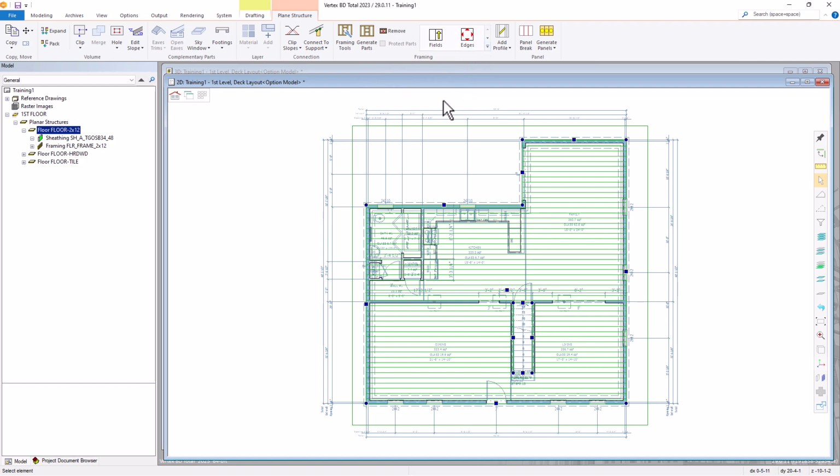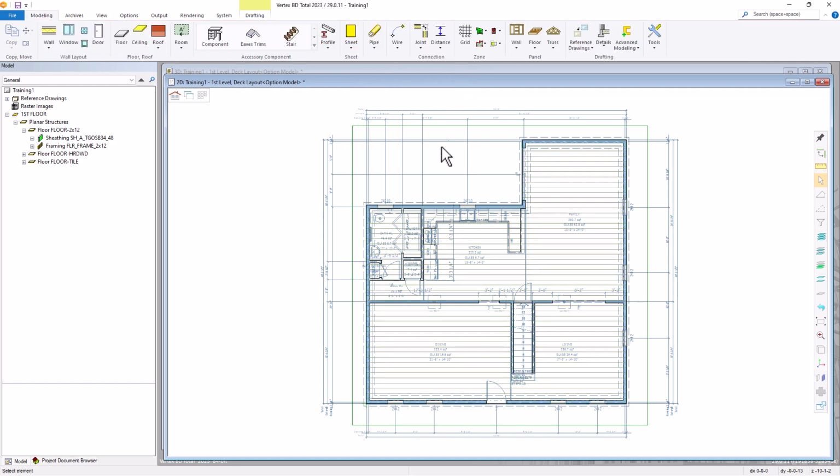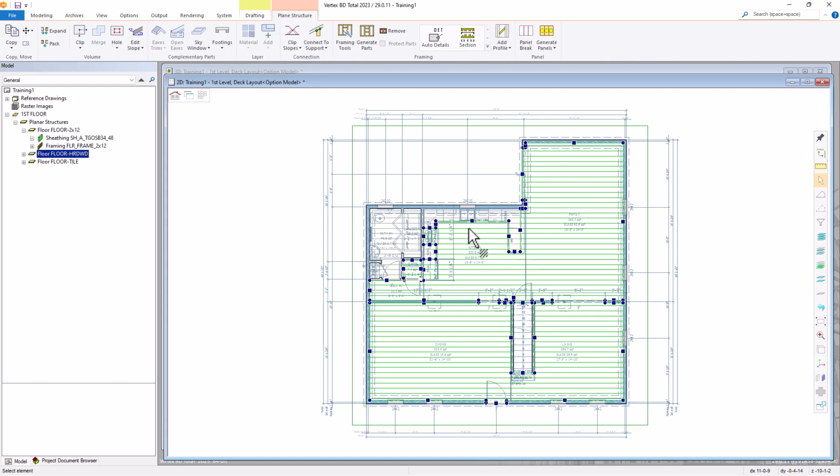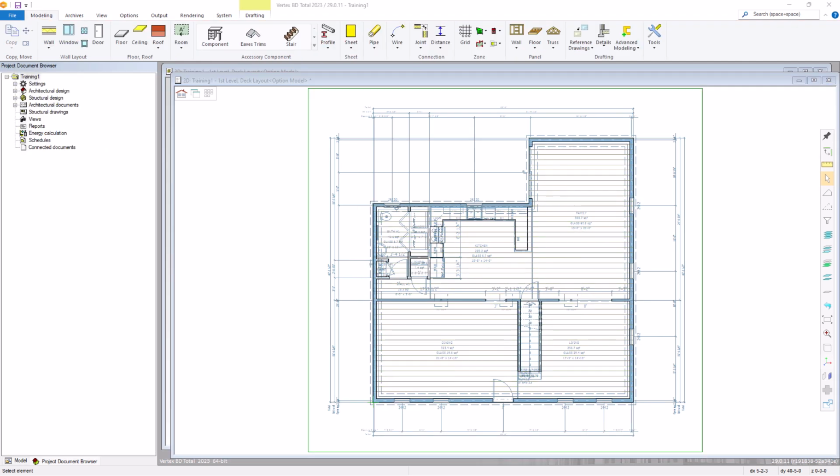If you select a different layer, like a floor finish layer, it will look something like this and have more grip points. This is indicating our selection of the hardwood floor layer that we added earlier in this model. When you look at the framing menu, the fields and edge tool is not visible, indicating that you did not select the floor framing layer. If you select the wrong layer, continue selecting layers until you pick the correct one. Hit Escape to cancel that selection.